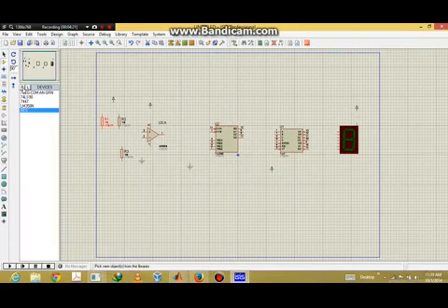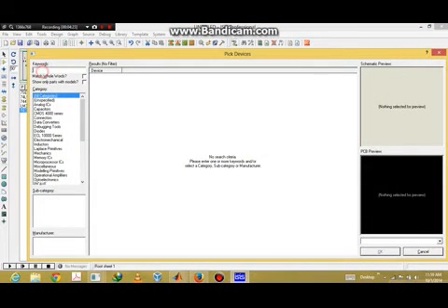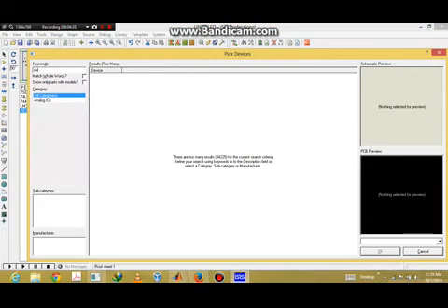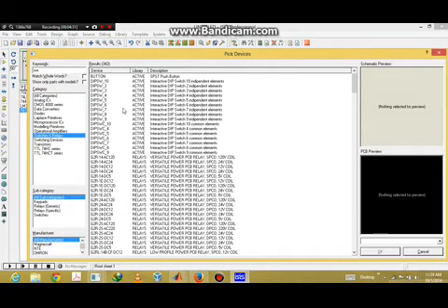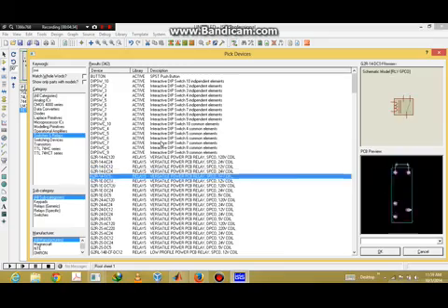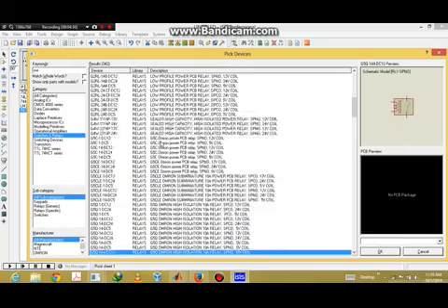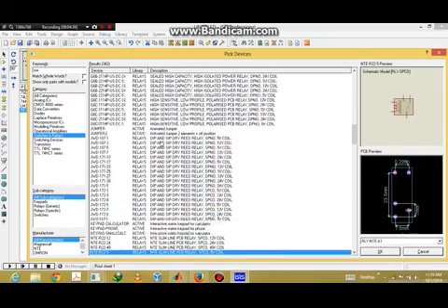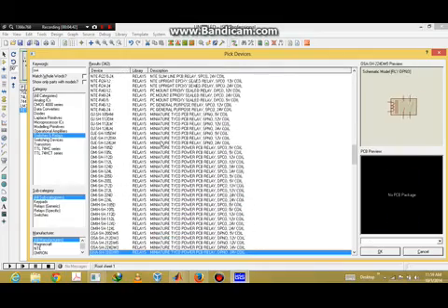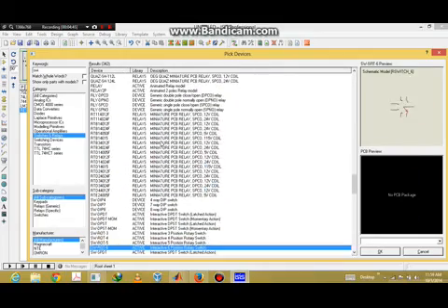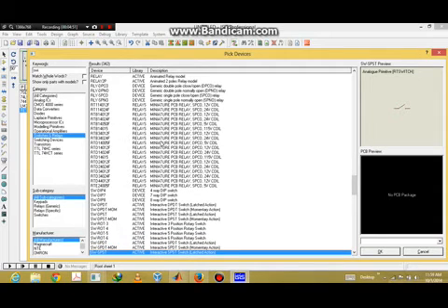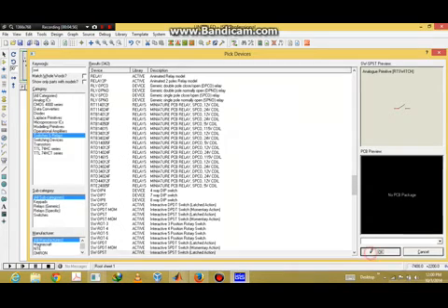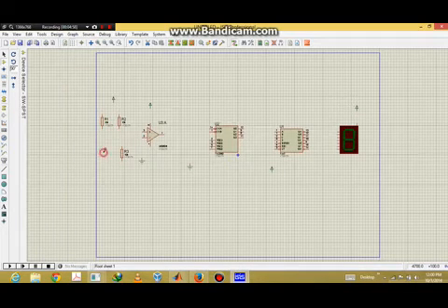Now we will place another component, that is a switch. Go to the switches and relays option. Now click any one and then look for SPST, that is single pole single throw. You can observe the schematic model. From that you can choose properly which one you want, that will suit your circuit requirement. Here we can observe that we have selected an active interactive SPST switch. Click on OK button. Switch is selected.